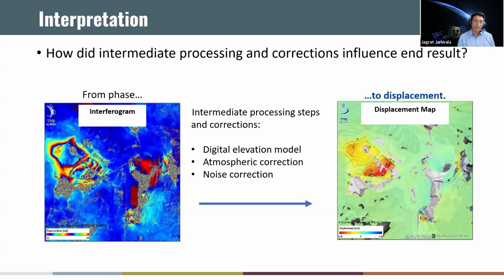And then the InSAR engineer uses assumptions to work with atmospheric and just inherent satellite imagery noise. Those need to be communicated to the civil engineer to understand how confident folks can be with the displacement maps and movement estimates that the InSAR engineer comes up with.